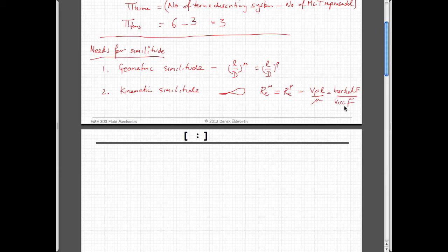That's all it is. It turns out to be those units. And this is some length, it could be the wingspan as well. It's some characteristic length. Of course, if the wingspan is scaled in the same ratio, it doesn't really matter what the unit is. It's just that when you measure things on your model, the parameter that you'd use to measure the Reynolds number would be the same on the model and the prototype. And you'd like it to be a relevant number.